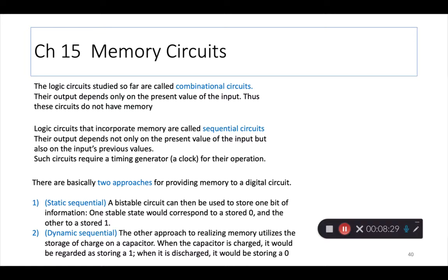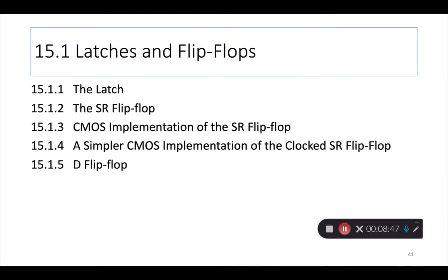So every so often, maybe once every clock cycle or once every 5 clock cycles, you have to put one more burst of charge into the capacitor, and that recharging process is why we call it a dynamic process.